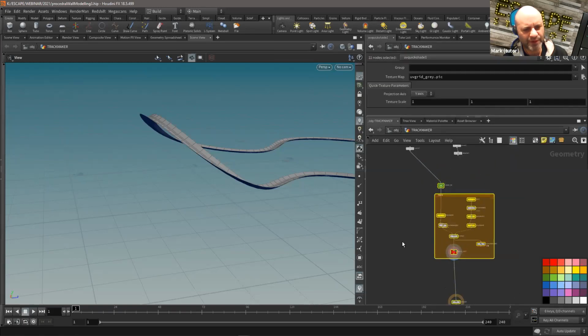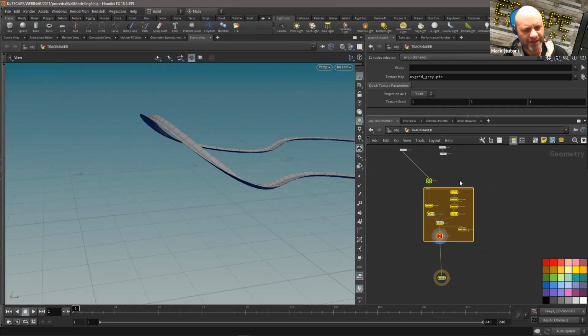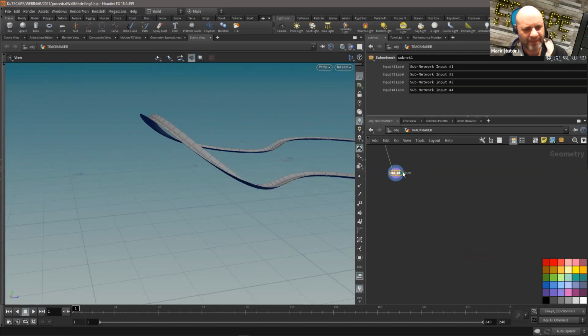So the tool belongs between these parts here. I'm just going to select all these nodes. To make a digital asset or a tool in Houdini, there's 2 steps. The first one is here. You've got to click on this cardboard box to make a subnet. There we go. And I like to give it the name of my asset now. So we'll call it WB track asset 2.